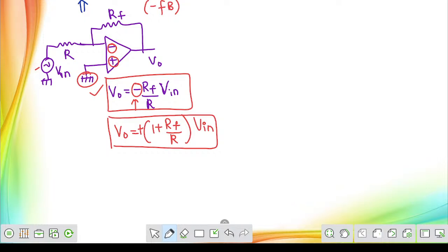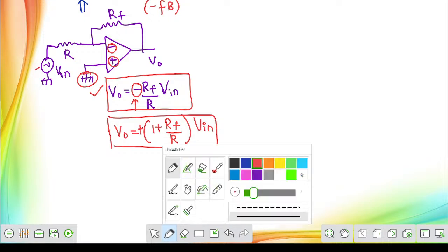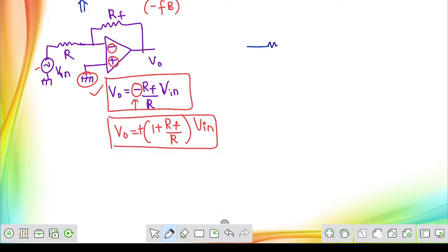Now, based on the concept of virtual grounding, we will design many different applications. We can design the voltage follower circuit, the summer circuit, the anti-logarithmic circuit, and different circuits. You can just recollect those once. But my suggestion is don't memorize anything. Always remember one thing: suppose an operational amplifier is given to you with negative feedback, apply a simple rule. What simple rule? Negative terminal, non-negative terminal. See, okay, the input voltage will be given here simply.